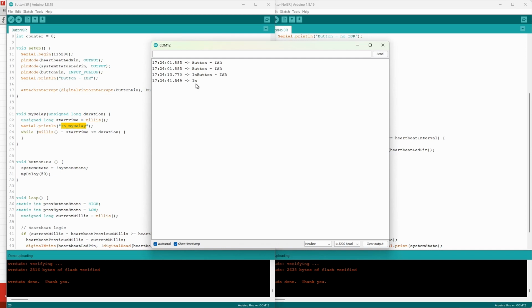So there's an opportunity then to put the second character into the hardware, or the UART, or is it a USART? Whatever, a USART or a UART. And so two characters are sent to the hardware ready for sending. And when it's finished sending, or basically when the data register is empty, because it started sending the character that's stored up in it, it'll generate an interrupt that says, hey, give me the next character. But because interrupts are disabled, we never get that next character, and that's why we just get two.